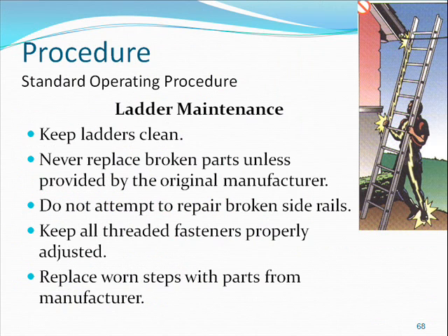Ladder maintenance. Keep ladders clean. Never replace broken parts unless provided by the original manufacturer. Do not attempt to repair broken side rails. Keep all threaded fasteners properly adjusted. Replace worn steps with parts from the manufacturer.